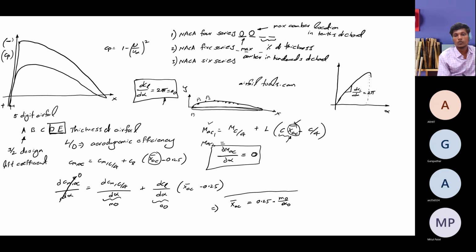Why do we need the aerodynamic center? Because it gives a point where your moments are not changing. So it will help you for designing of an aircraft or for stability purposes. It is very required because forces can vary, but moment should not vary. For flight stability or any aircraft stability purposes, these parameters are so useful that you can go through in the next stability courses you take. You can understand how the aerodynamic center and center of pressure are very important for designing the aircraft. So this is up to the concepts that we covered for